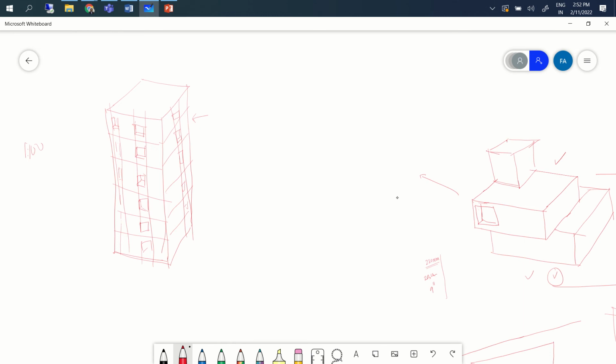The wall is going to be the same for all the floors. So don't be lazy and just randomly do it like I am doing. What you need to do is draw a guideline and add the wall thickness. What else can be done by the people who are doing this kind of thing? You can of course add the headroom. Let us first add the terrace, the parapet wall, and probably let's say there's a headroom.